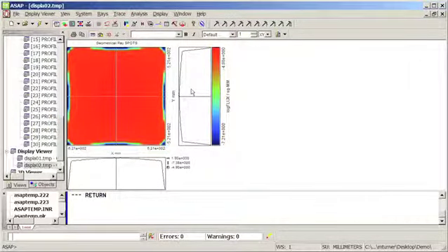And you'll notice at our detector location, we have a very uniform square distribution of energy. The key of this example was to show you that sometimes it's more important to determine what a smart and effective merit function is. If we had traced a very, very large number of rays, such as we see right here, we would have reached the same solution, but it obviously would have taken a great deal of time. If we develop merit functions that are more efficient, simply by tracing a few rays in this example, you'll be able to get an optimized solution in a very short period of time.